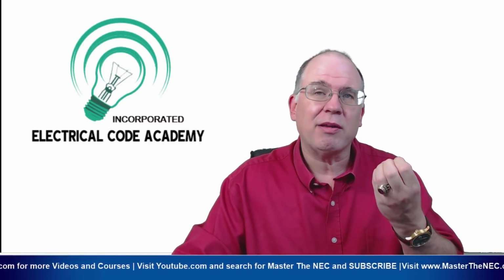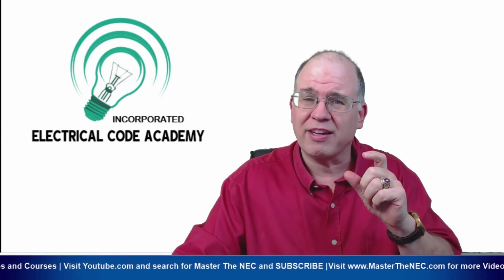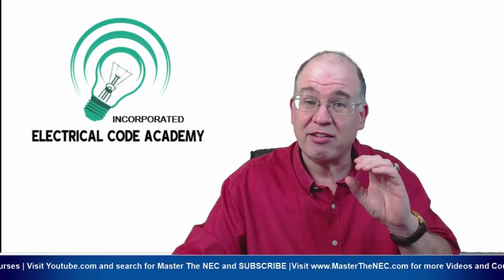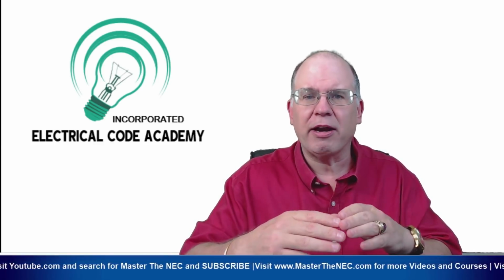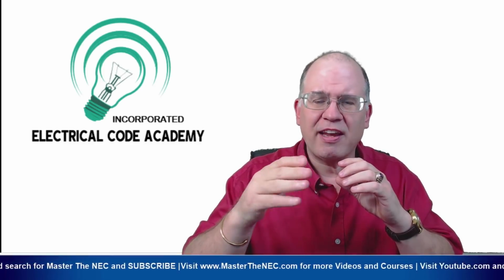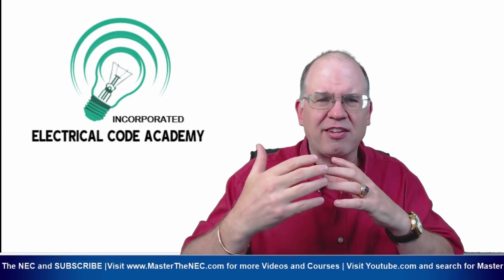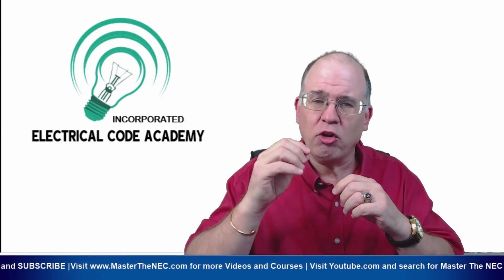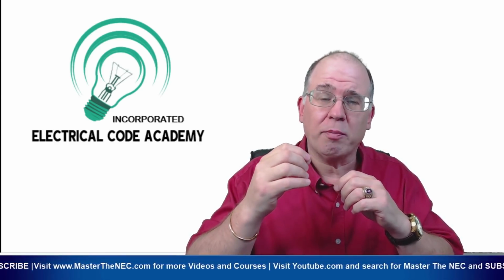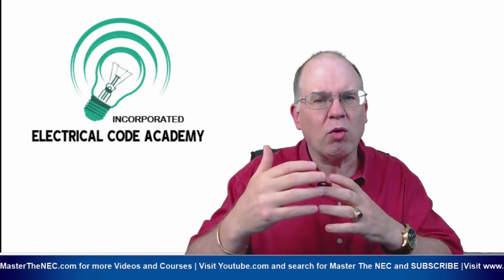But let's say you have a multi-wire branch circuit where you're using a 2-pole breaker or 2 individual circuit breakers with an identified handle tie that keeps them right next to each other, so that ultimately the breakers are on 2 different legs within the panel. And you use a multi-wire branch circuit, let's say a 12-3 or 12-2, and you're sharing a neutral. Based on the cancellation effect that takes place, that neutral will carry the imbalanced load between leg A and leg B. And it means that you won't overload that neutral.